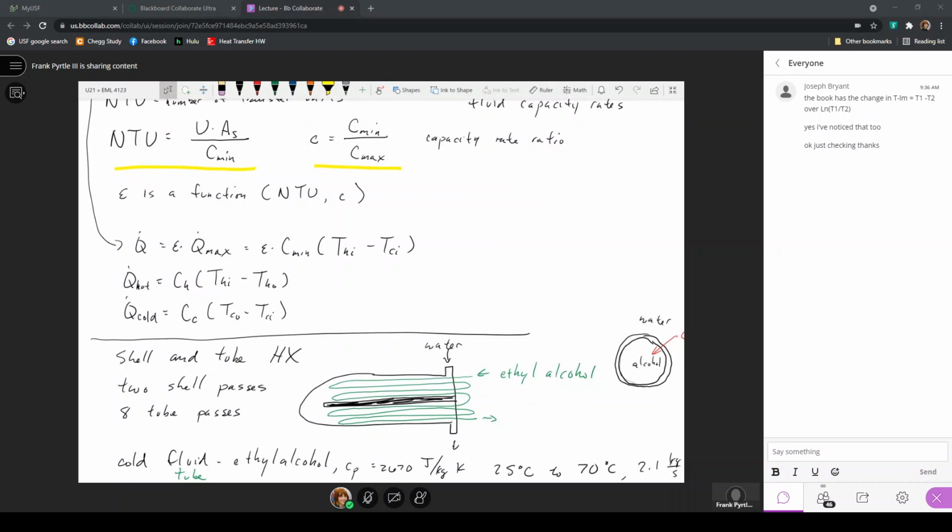If you're given a particular heat exchanger with a known value for an overall heat transfer coefficient, often the effectiveness NTU method is a little bit easier to use to find what the outlet temperatures would be if they're unknown. But for either one, you can do both.